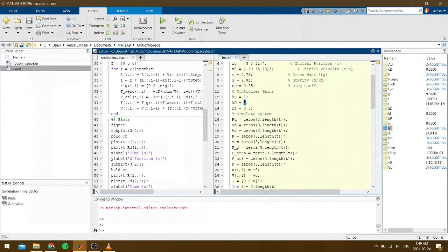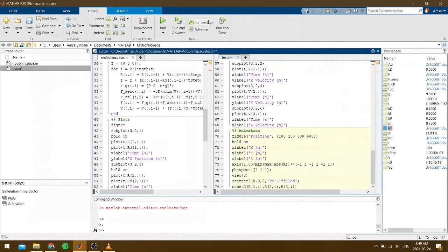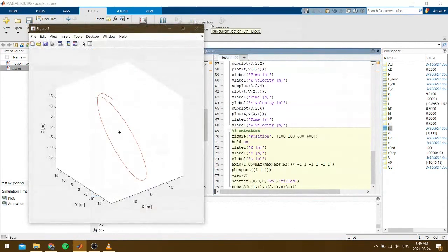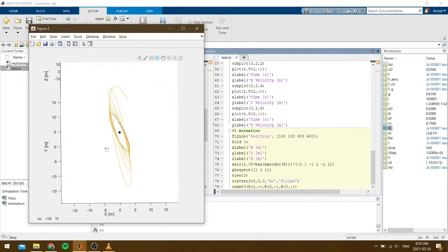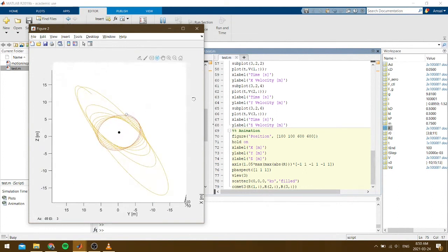And let's just turn down some stuff. So what happens if I turn down my proportional gain and my KD and stuff? It should take longer to converge. And yeah, that's what we see. You can see that slowly over time, it's going to decrease. And actually, this is probably going to take a really long time. And our Ki is not enough for it to converge.